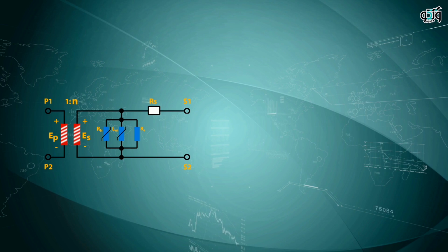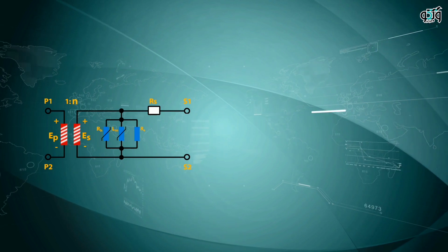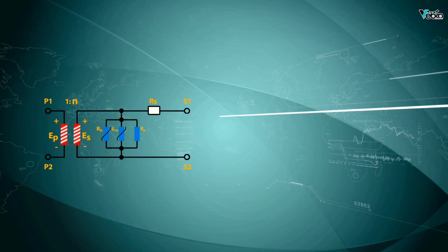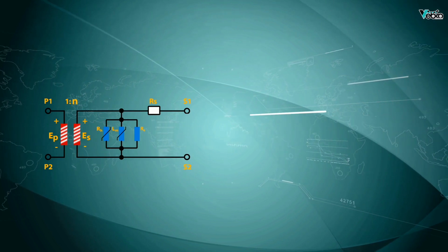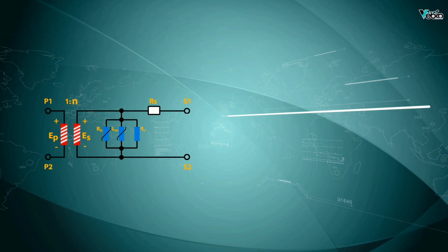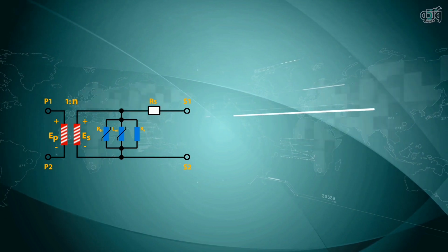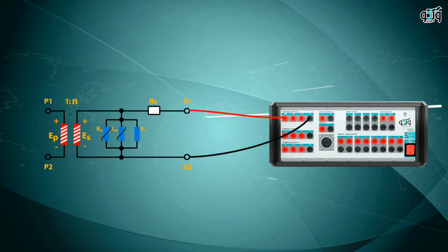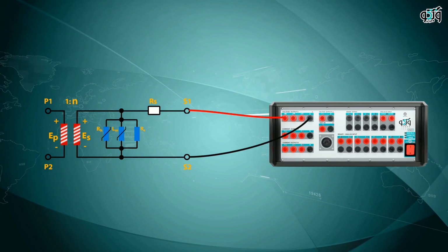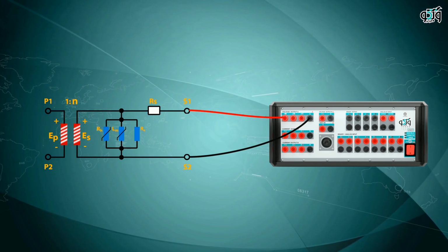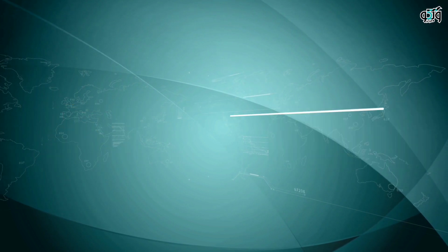Rs indicates the resistance of the CT. In the parallel branch, Rd and Rh stand for Foucault and hysteresis losses of the coil, and L stands for the magnetizing inductance of the CT secondary. To perform the excitation test, the secondary of the CT is fed by voltage and checked to see what nonlinear element is causing the CT to show a nonlinear behavior even in lower voltages.